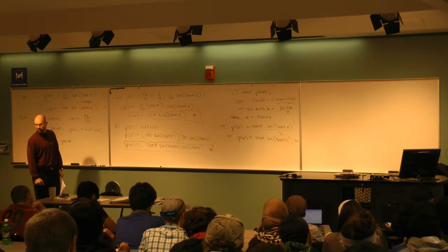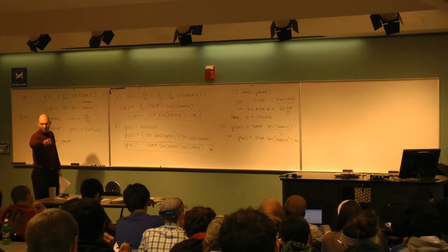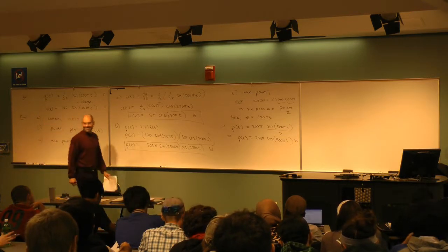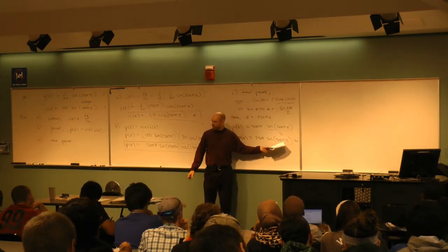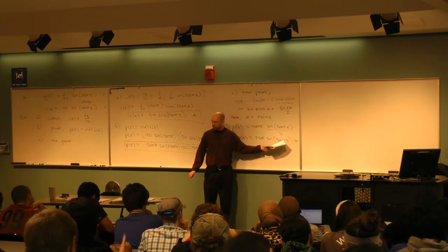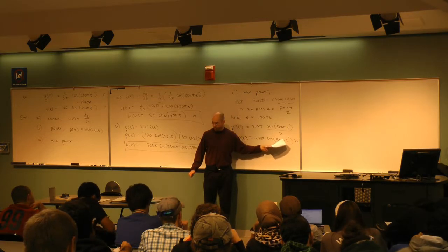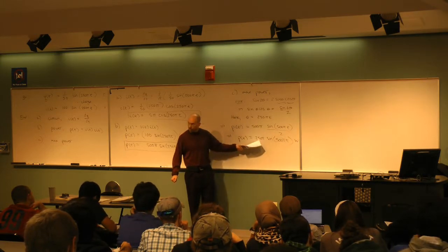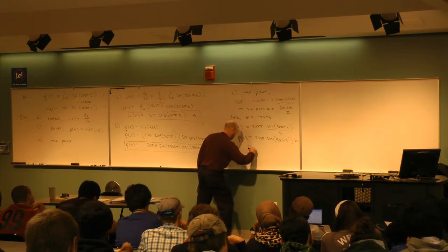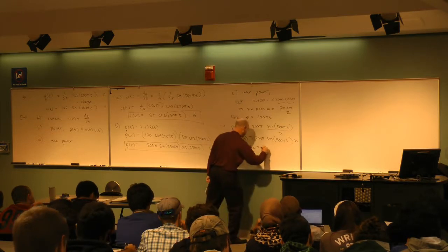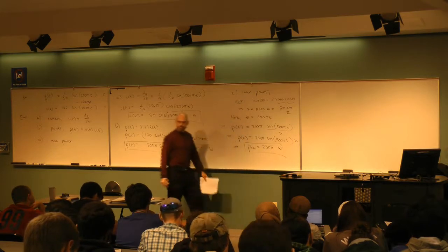Do I need calculus to get the max power? Got a yes over here and a no over there. What do you think? Amplitude. All right, I don't care what the frequency is. Sine function oscillates between what two numbers? 1 and minus 1. Does not matter what the argument is, right? 1 and minus 1 is the sine function. The number out in front is the maximum. Okay, so no calculus required for this one. P max is equal to 250 pi watts. Okay, that's it.